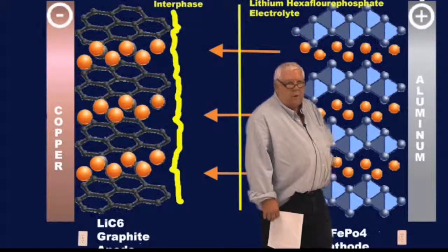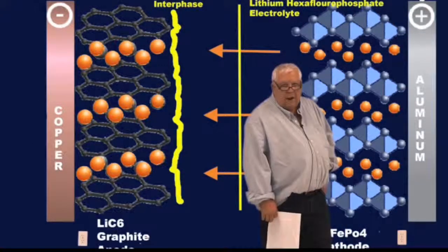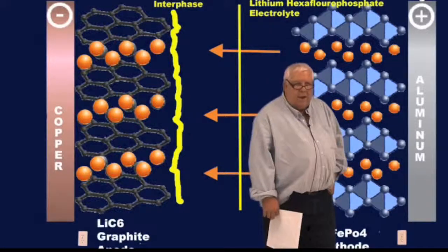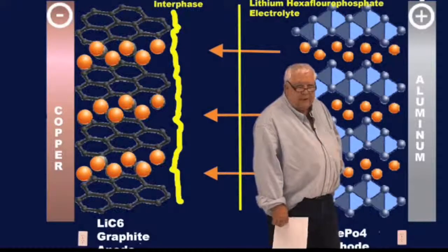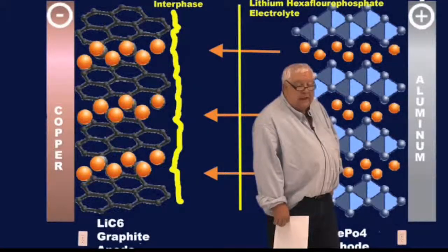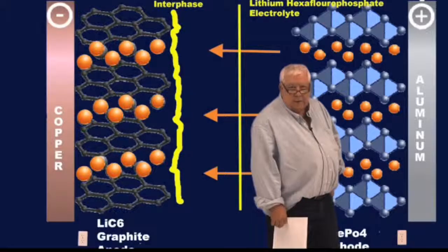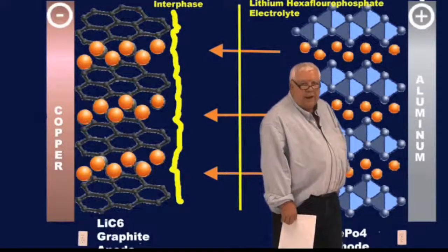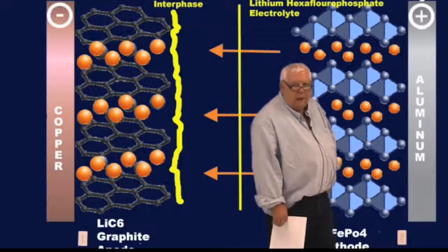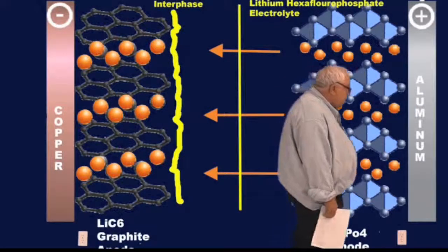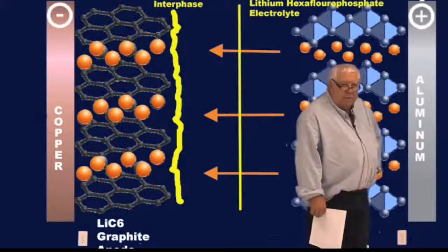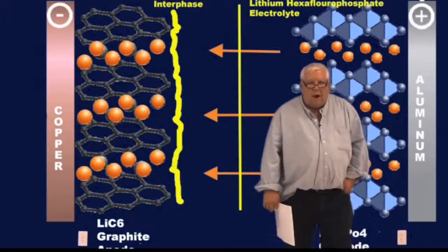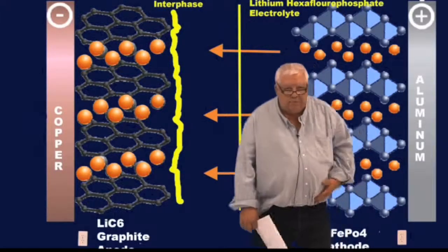There's also a lot of magic sauce out there. Every battery manufacturer has various dopants that they think will increase conductivity of lithium iron phosphate. Yttrium is one, vanadium, molybdenum, cerium, and so everybody has their magic sauce that they will not tell you what it is they put in there, but it's usually some rare earth element, metal, that they put in the lithium iron phosphate to make it more conductive.